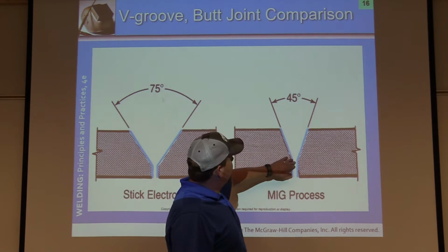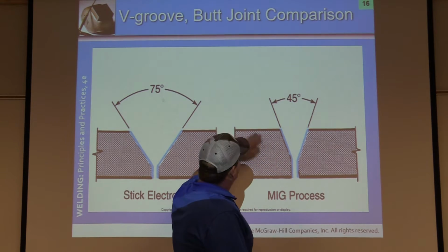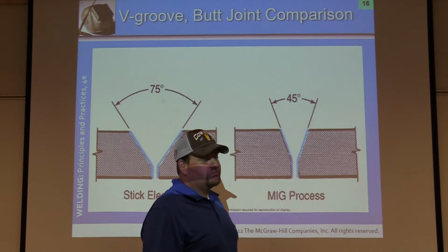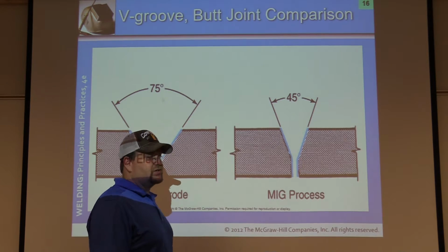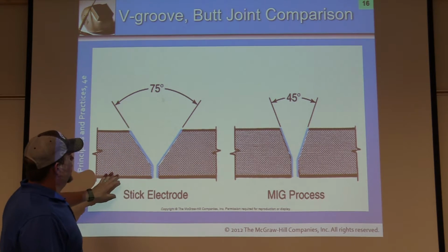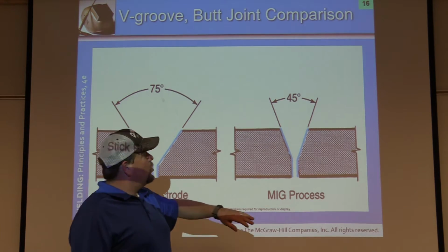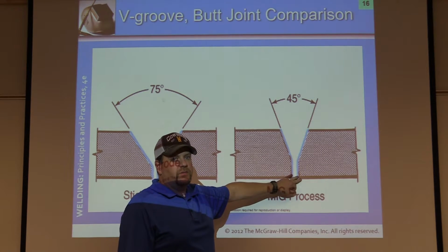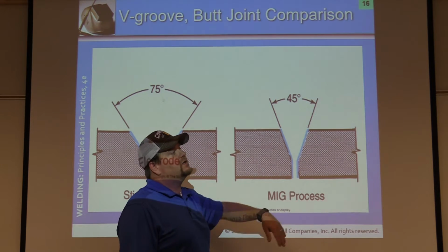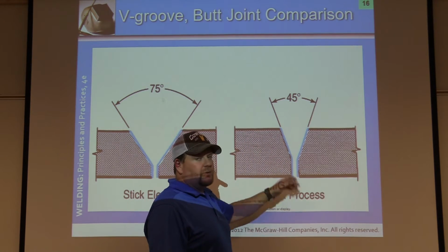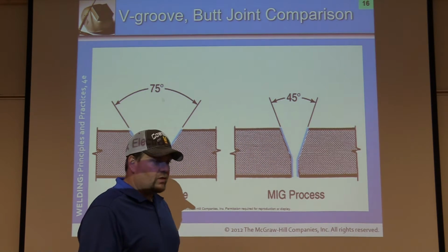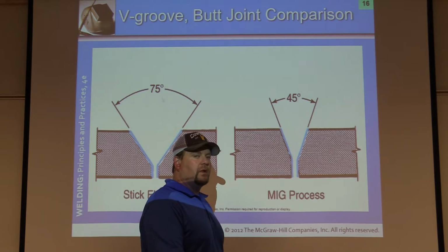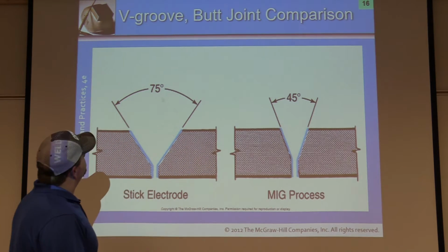If you need to take it back to 65 degrees or 75 degrees for wire, do the same thing. It literally takes just a second longer, okay? And then as you gain more and more skill, this becomes much easier. Do not hang up on this at the beginning. As you get more and more practice, you can start cutting your angles, being a little bit steeper. You know how to get away with a little more things. You've got a little better manipulation, so forth, okay?